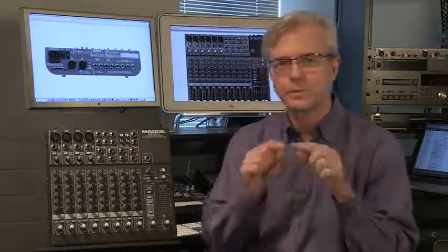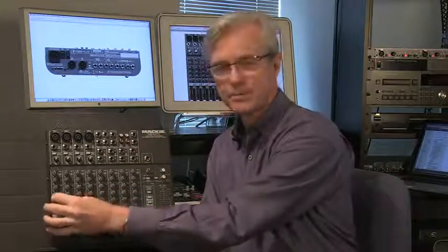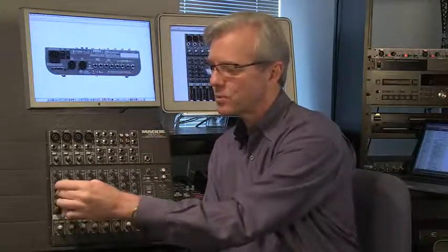And then I would have another one which would control the range of frequencies around it, how wide that spectrum is. So a good parametric, you would have 3 knobs for each range. You could set the center frequency, you could set the width of effect, and also how much amplification and attenuation happens. And so then the more bands you have, of a 4 or 5 band parametric equalizer, then you really have control over changing the sound where you want.